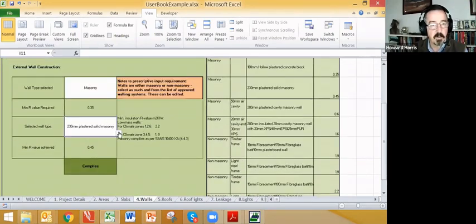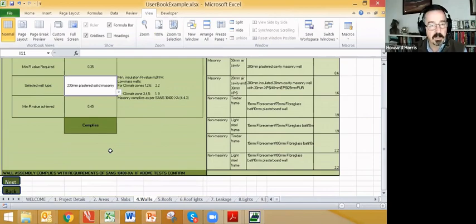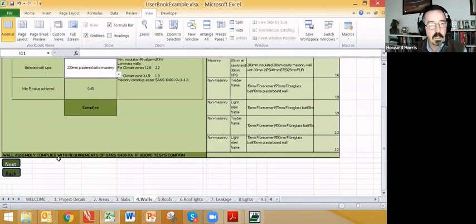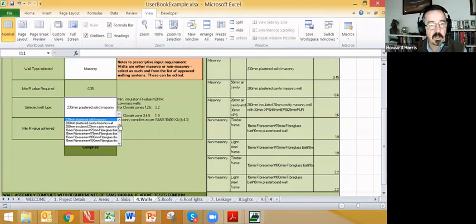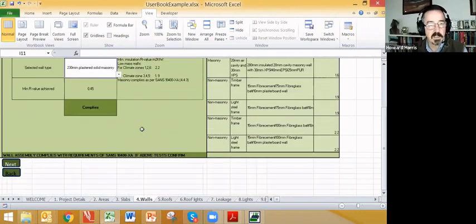We do set out some options that might meet this requirement, and there are hollow concrete blocks and some plastered walls. If you could just select the closest approximation to that particular wall, it will show the compliance message. I think if there's any deviation in your wall structure from any of these pre-selected descriptions, one would need to put in the closest and then have it obviously detailed in your plans as to what the exact construction might be.